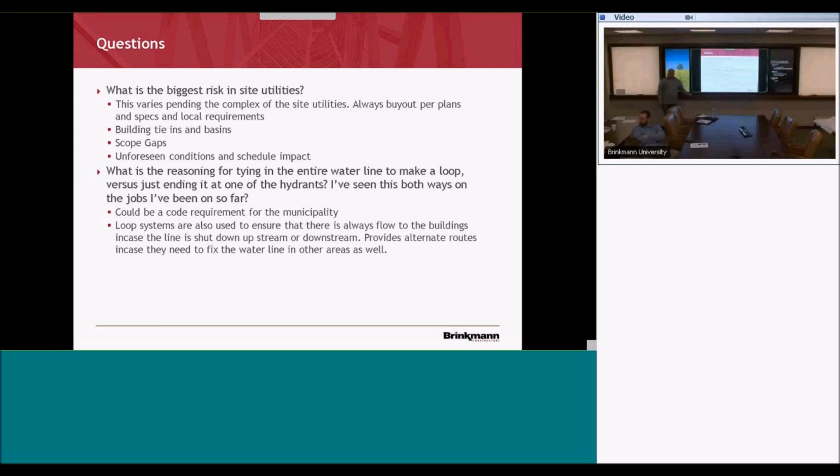Ran into trash pits, borrow pits that were filled with topsoil. I could write a book. So, put it in your pricing and just make sure you get a soils report. So was that a negotiated job then? On that? Yes, kind of. It ended up being negotiated down to a lump sum.